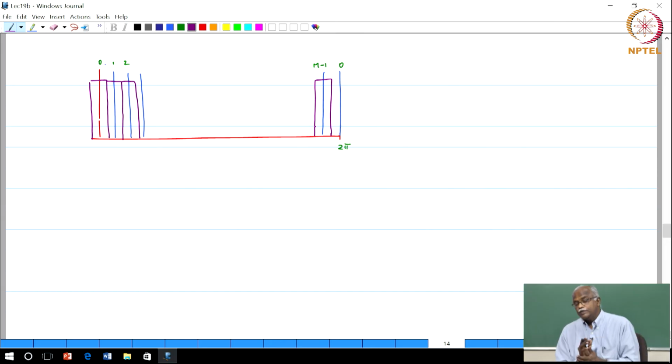So, what is the OFDM transmitter actually doing? It says, channel number 0, you please transmit for me symbol S0, some QAM symbol; channel 1, you transmit S1; you transmit S2, and so on. This is an FDM signal. And at the other end, what would you do? You would do the inverse operation: convert it from a center frequency back to baseband and then pass it out.